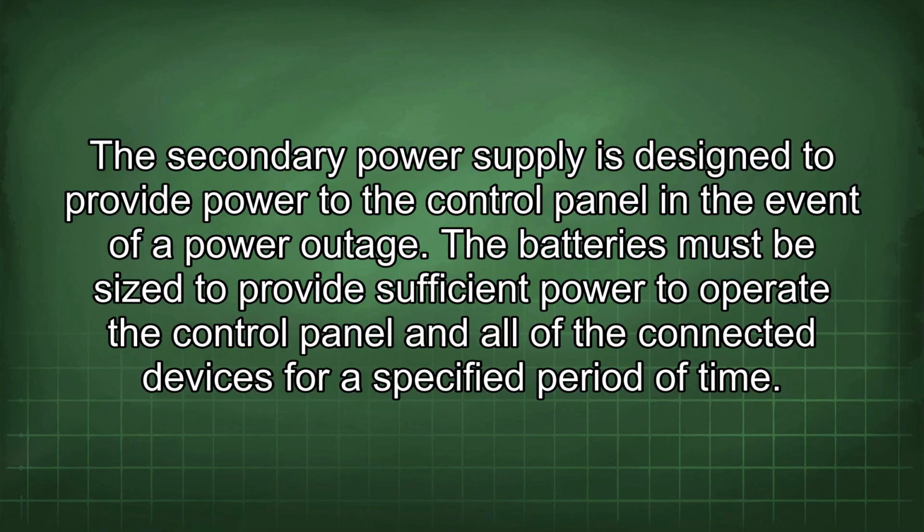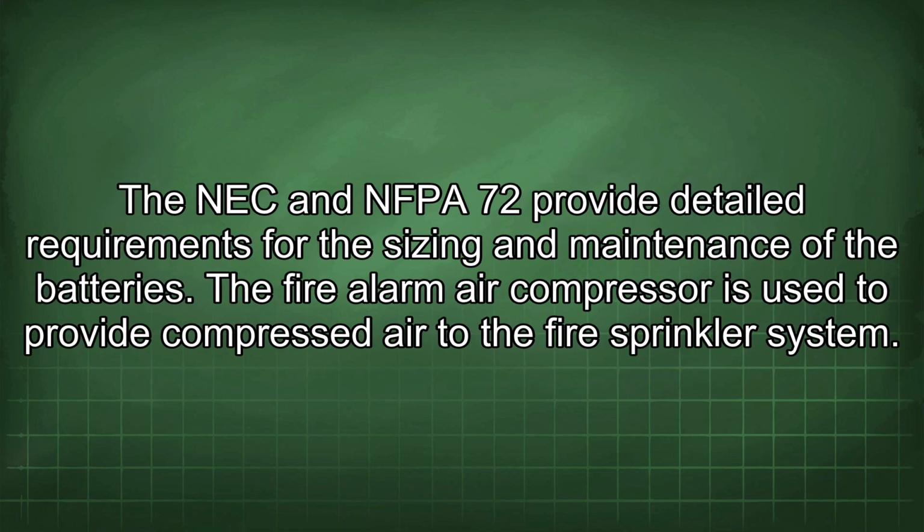The batteries must be sized to provide sufficient power to operate the control panel and all of the connected devices for a specified period of time. The NEC and NFPA 72 provide detailed requirements for the sizing and maintenance of the batteries.